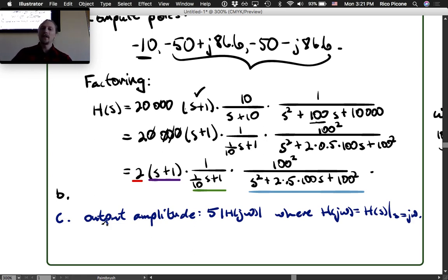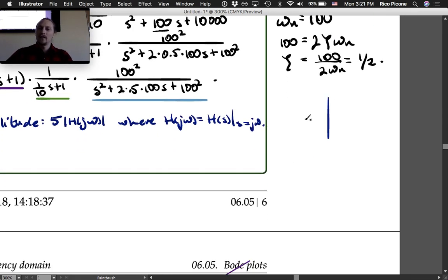And then we have to take the magnitude of it, which is to say you could use the Pythagorean theorem, square root of the sum of the squares, real squared plus imaginary squared, right? So complex plane, real, imaginary, H of j omega is this point. The magnitude is the length of that, and the phase is the angle there. So find the magnitude of H.